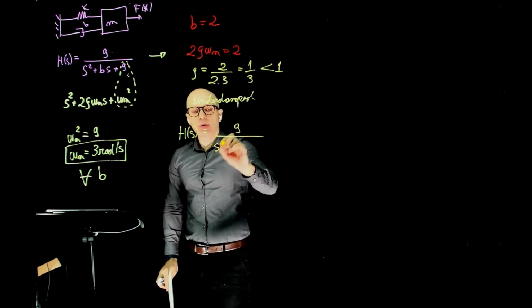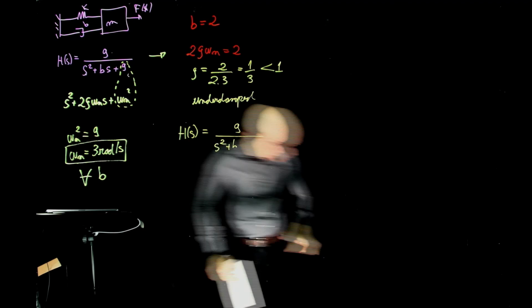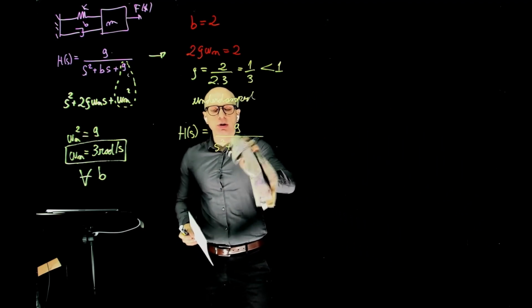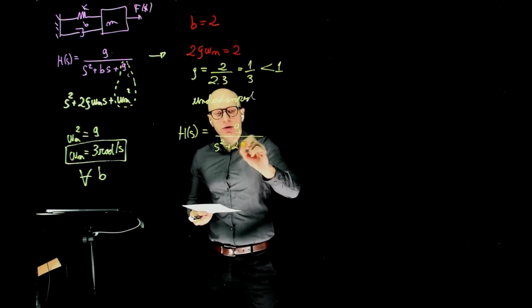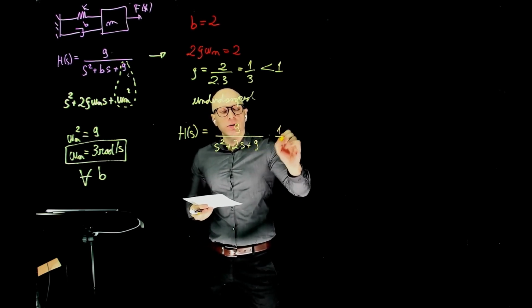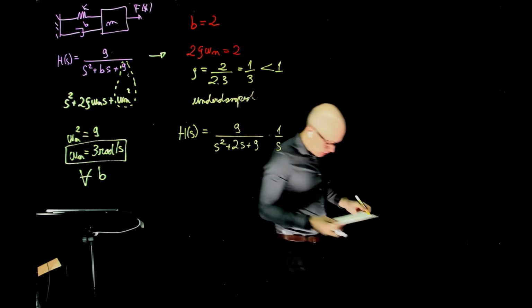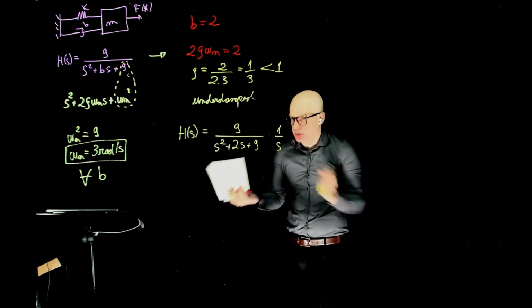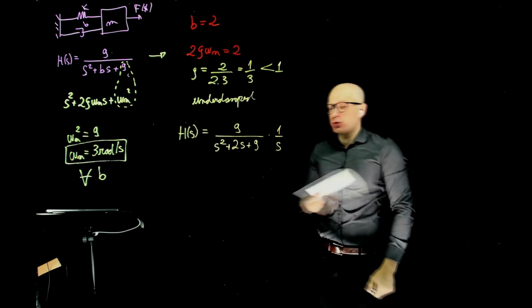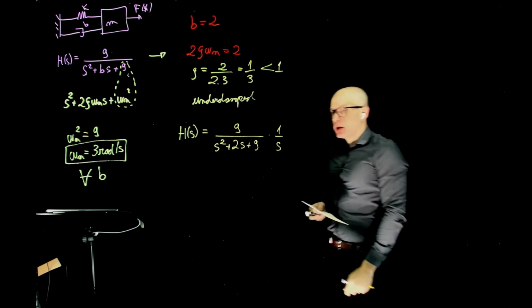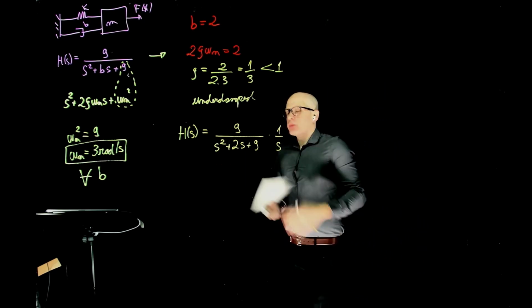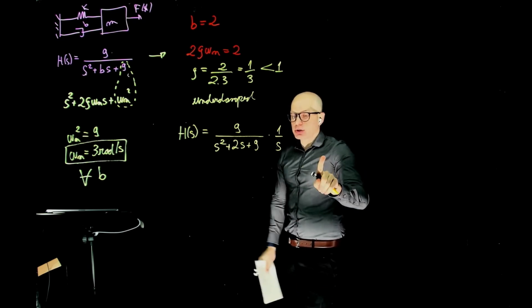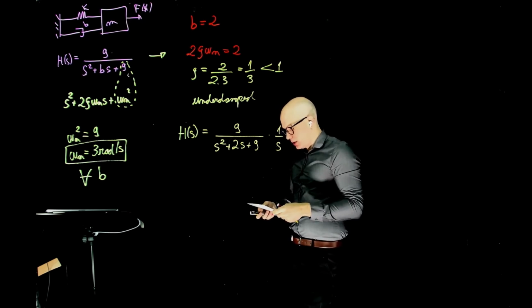And because of that, we cannot split this polynomial into any other format. Well, we could factor out the roots, but then the roots would be imaginary numbers. We can still do that, but it would be a little more complicated than what we want. We could write this as a function of 2 imaginary roots. That's perfectly fine. Do partial fraction expansion with that, and then solve for the inverse, that works. But we cannot split this into real poles as we did before. So our transfer function will have to be split into partial fractions now, considering this polynomial entirely as it is.